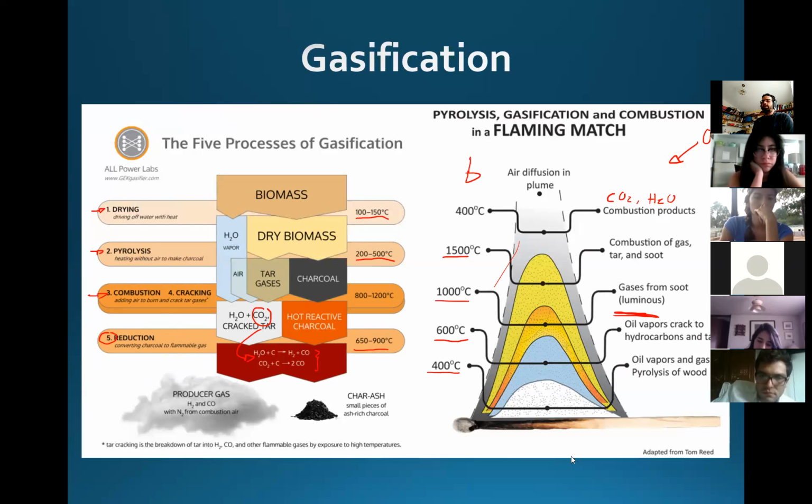Well, many times you can see it in the temperature of the flame. If you know that a process has a complete combustion and you don't know if it's starting to burn incompletely, what you can do is compare the temperatures, for example, in the chimney gases, because when you burn with incomplete combustion, you obtain less heat than with complete combustion.